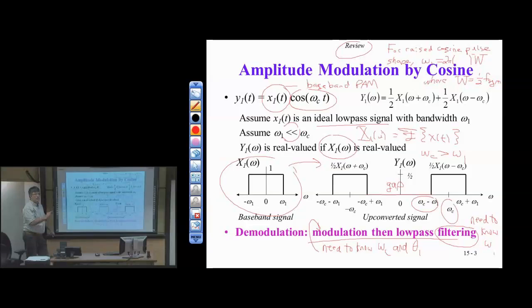There's no sampling yet. There's another parameter in the raised cosine. Alpha, right? The roll-off factor. So what's in that parenthesis? 1 plus alpha. And alpha is this roll-off factor that has value between 0 and 1 inclusive.